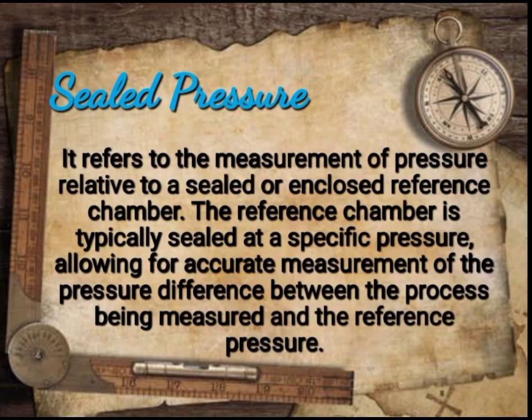Next is sealed pressure. It refers to the measurement of pressure relative to a sealed or enclosed reference chamber. The reference chamber is typically sealed at a specific pressure, allowing for accurate measurement of the pressure difference between the process being measured and the reference pressure.